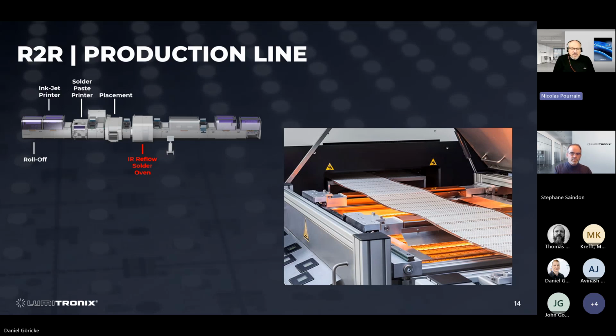Step 5 is very important. This is the oven. In this case, it's an infrared heating element with zonal temperature measurement and control, with separate heating elements. It's very efficient and compact in size compared to a traditional oven. And this oven is a key element in the speed and the quality of the assembly, as you cannot use a traditional oven for this kind of manufacturing process.